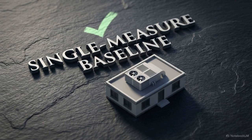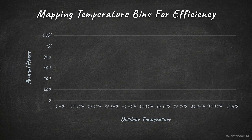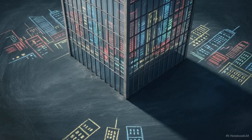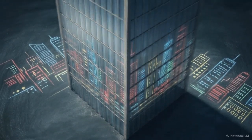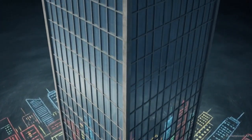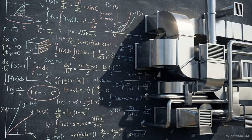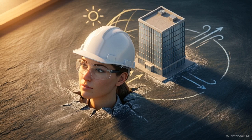The choice of model dictates the reliability of the analysis. For small structures with constant efficiency equipment, the variable-based degree day method provides a fast, accurate baseline. When equipment efficiency shifts with the outdoor temperature, the bin method maps those nonlinear variations across the spectrum of annual weather data. And for complex commercial facilities full of interacting feedback loops, simultaneous hourly simulation engines provide the necessary dynamic resolution. True energy prediction is an exercise in matching the engineering resolution to the complexity of the variables. When the modeling tier aligns with the building's thermodynamics, the resulting economic analysis moves from an educated guess to an engineered certainty.